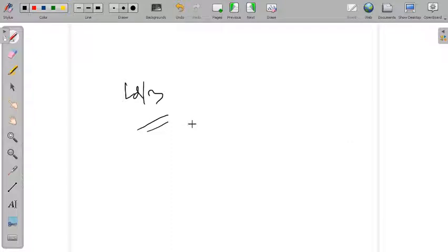Next, the diameter of the positive moment reinforcement shall be limited to a diameter such that the Ld computed for sigma s equal to fd does not exceed the following. Let me write the equation and then I will tell you what is given here.